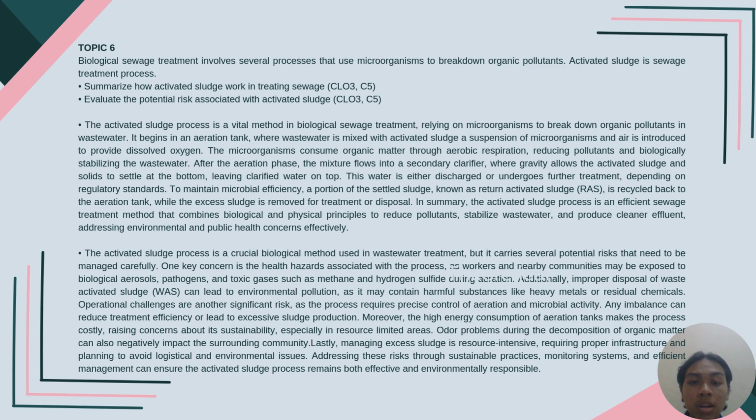Lastly, managing excess sludge is resource intensive, requiring proper infrastructure and planning to avoid logistical and environmental issues. Addressing these risks through sustainable practices, monitoring systems, and efficient planning can ensure the activated sludge process remains both effective and environmentally responsible.